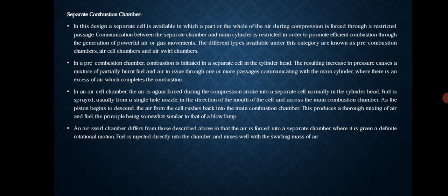The resulting increase in pressure causes a mixture of partially burnt fuel and air to issue through one or more passages communicating with the main cylinder, where there is an excess of air which completes the combustion.